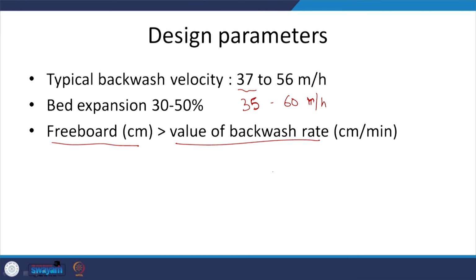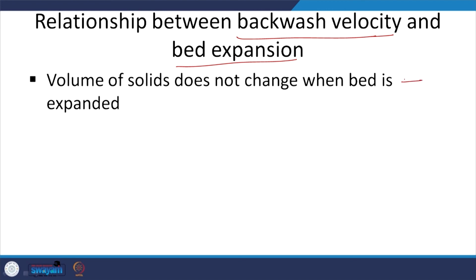Again, that is something to keep in mind. So, between backwash and bed expansion, obviously there is going to be a relationship which we are going to use later. Let us look at what it is. Again, this is what I was trying to say earlier, the total volume of the solids does not change. Now, the total volume of the bed has increased, but the volume of the solids within this total bed is still the same. That is something to keep in mind.